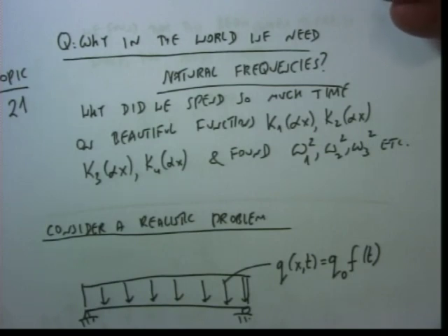Maybe you have any questions or discussions on this? Because that sounds a bit strange. Why could it sound strange? Because, look please, natural frequencies deal with free vibrations naturally. There is no loading. It turns out that a beam has an infinite number of natural frequencies, omega 1, omega 2, etc. Now when we deal with the response, these natural frequencies are very handy because we are expanding the solutions in terms of the modes.